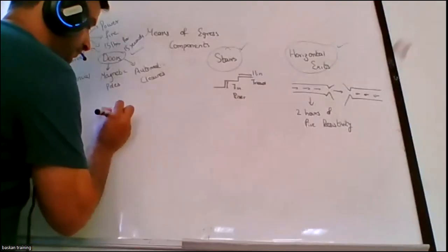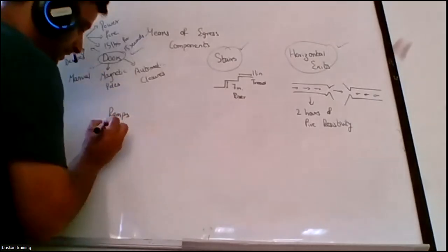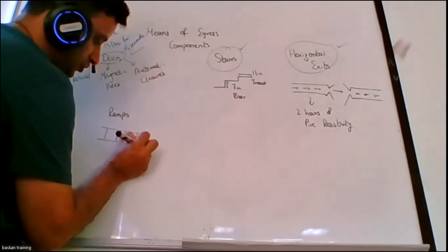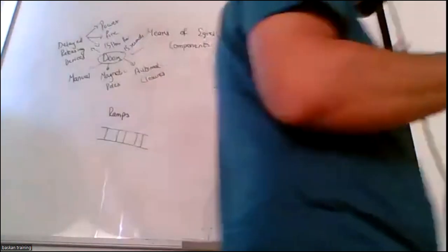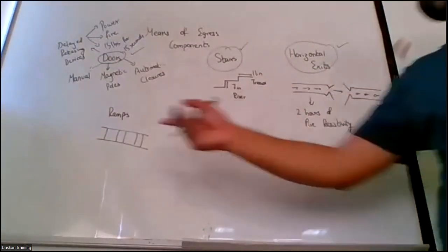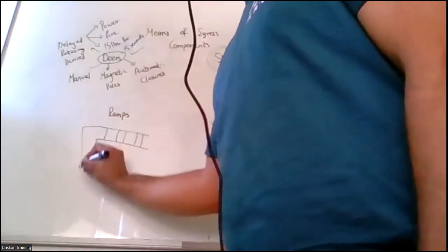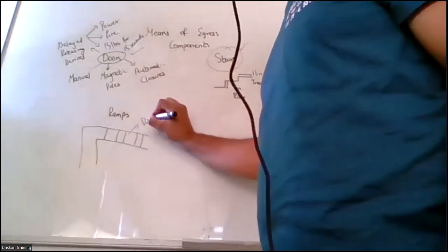Ramps. Various different codes are there for ramps, and the inclination should be limited to a specific point where a wheelchair can be used effectively to evacuate people outside the occupancy. But the ramp should always have resistance strips.